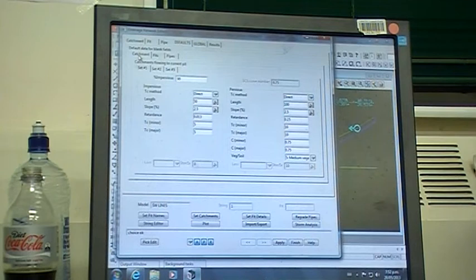The first is catchment. Again, it prompts us for a % impervious, so change it to 65. If they're all set to 65, you can't go wrong. Again, anywhere it prompts me for a C value.